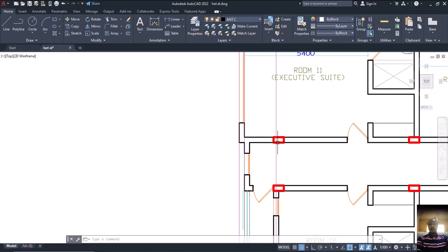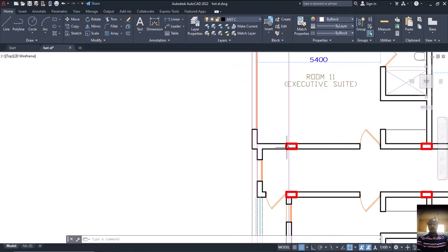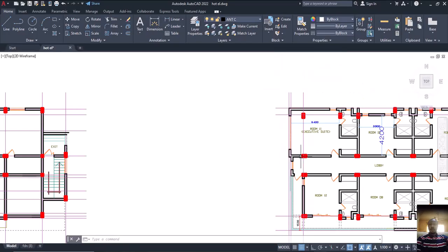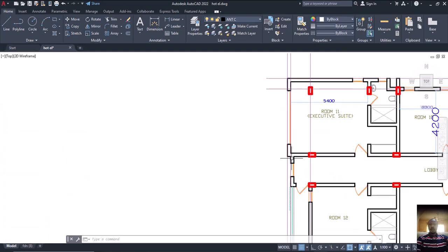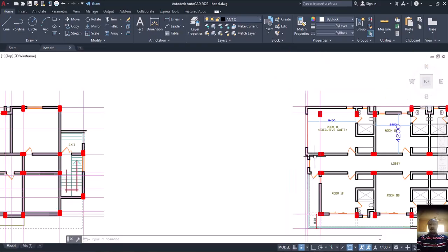So for me, I would love my structural element to be typical, to be aligned. And if you look from this edge to this place, it's not much. So I can extend my beam like this to run like this. I don't need to put a column here, though some can decide to put a column here, which means this column terminates at the ground floor and then proceeds.